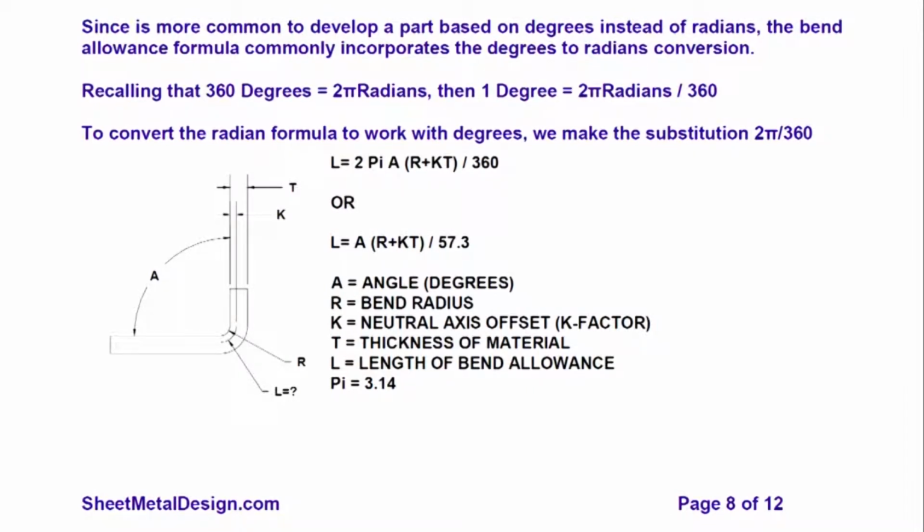So, what is done normally is, depending on the practice in the workshop, you usually have a table. In the case of what I have shown you, for all our 1.6 and 1.5 mm aluminum materials, an allowance of 0.65 millimeters is added to the internal dimensions. So, you have a simple L, I have limb A, I have limb B. Suppose this is 40 mm and this is 40 mm, I take the two internal dimensions straight away. Mind you, I am not talking about the clamping position, I am just talking about the flat length. When it is laid out, how much flat it will come.